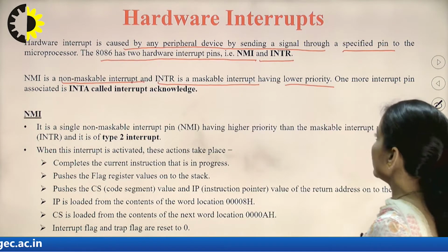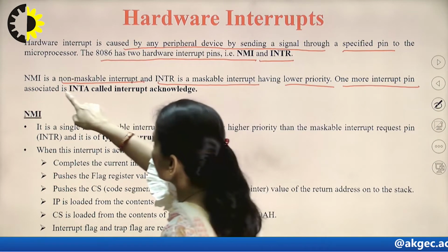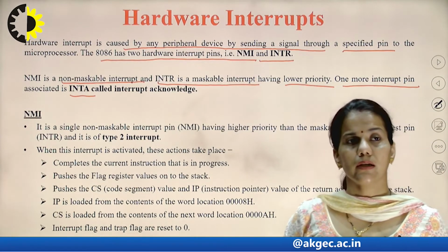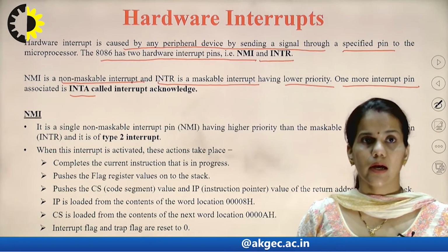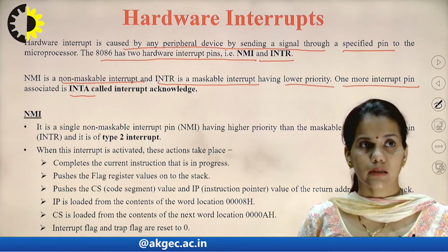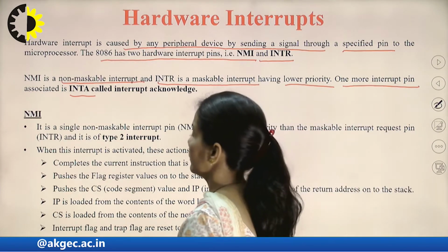And in return to these interrupts, there is one more pin, that is INTA, that is interrupt acknowledge. So whenever the interrupt arrives on the processor and the processor acknowledges it, in return it sends a signal on the INTA pin. So that is the interrupt acknowledgement pin.